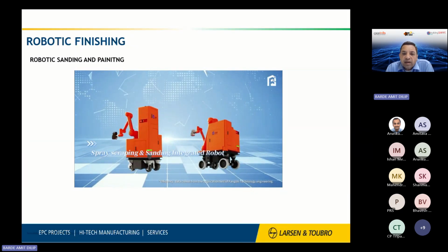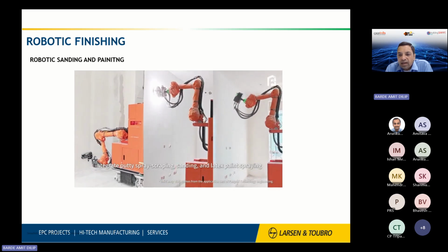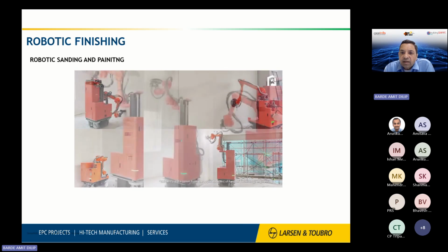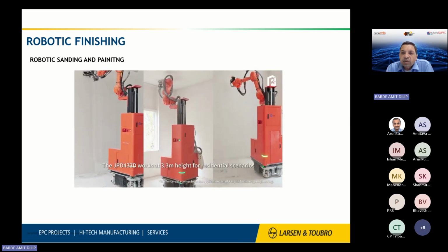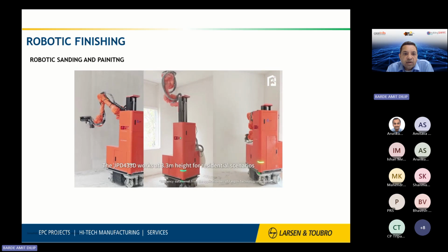This is that automatic painting and sanding machine. Now, because we are using precast and those battery mold good-finish panels, you can automate the sanding and painting because there is not much work involved, no lot of manual intervention needed, because the surfaces are already good.